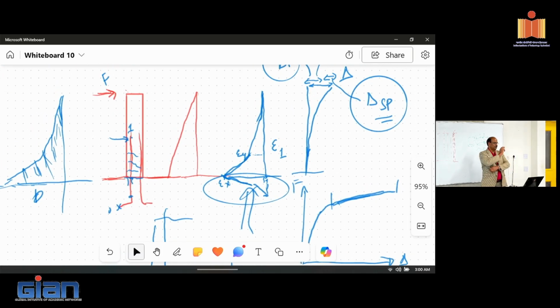Actually, because you put a coupler in the first configuration, your effective strain distribution is going to be lesser. So the effective strain integrated for the curvature is also going to be lesser above the column. So I would expect delta F to be lesser.